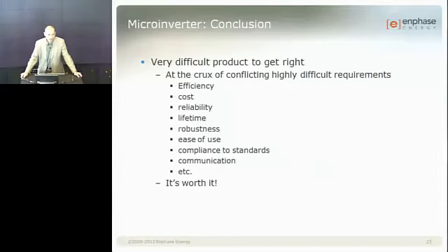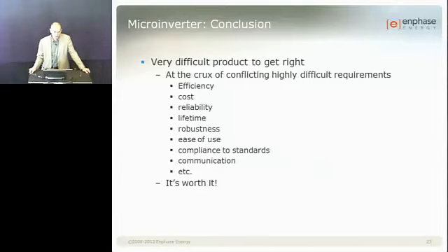So DC-DC converters, yes. That concept is, actually, newer than the microinverter, because the microinverter concept started in the mid 90s. Some people indeed do the MPPT at the DC-DC converter level. So they have one DC-DC converter per unit. Let's say you get 30 volt in, 8 amps, you'll get 25 volt out, 10 amps, or something like that. And the MPPT is down there, and the inverter now only does the DC to AC conversion, right?